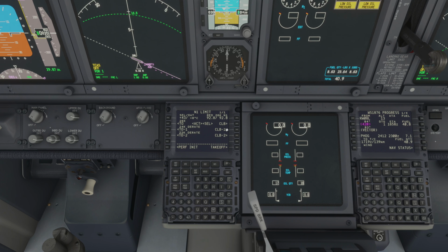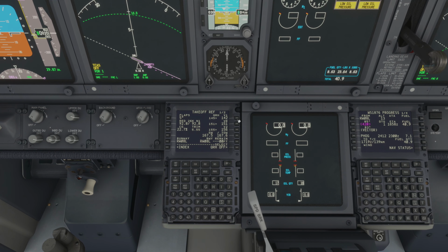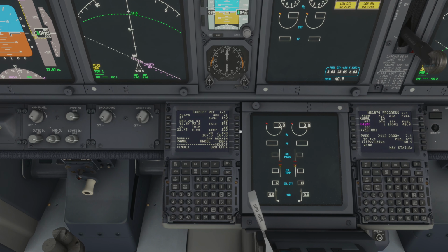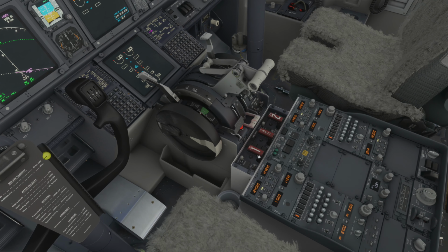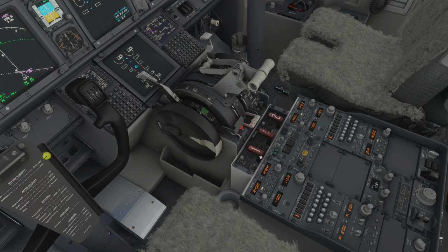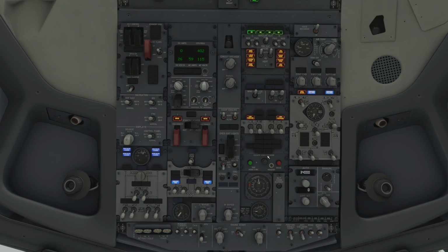43 degrees assumed takeoff. Takeoff speeds are V1 142, VR 151, V2 156. CDU preflight is complete. Rudder and aileron trim free and zero. Taxi and takeoff briefing is complete. Anti-collision light is on. And we got the go ahead to release the brake for pushback.